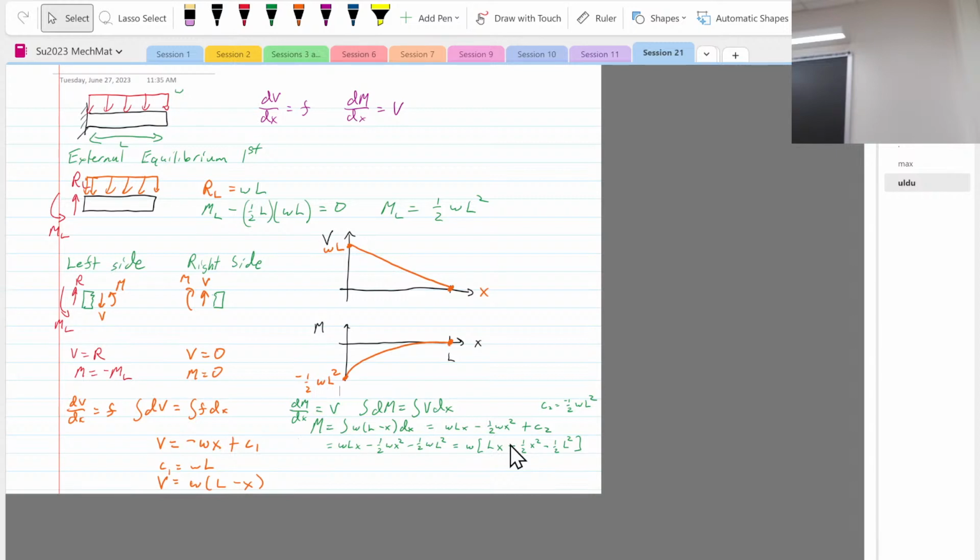Twisting has to do with the direction, like it's on a rod or shaft, versus bending, which is about what is happening with the deformation. If I take this eraser and apply a twisting force out here, I can see it's going to cause it to twist like this. That's definitely twisting, a force acting some radial distance, which is causing that. But if I move it over here, you see that this is causing this thing to bend. So that's not twisting, it's a bending moment, applied with this length of action, not this offset from the middle.